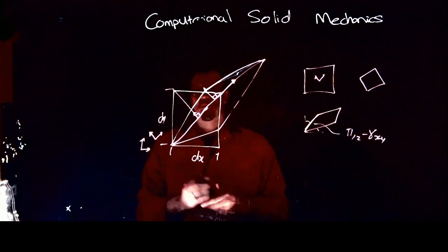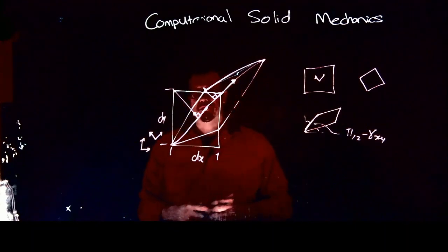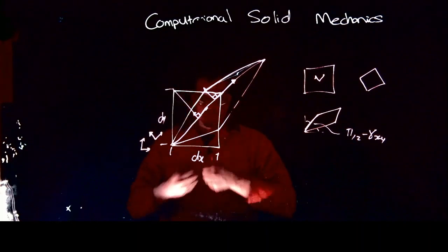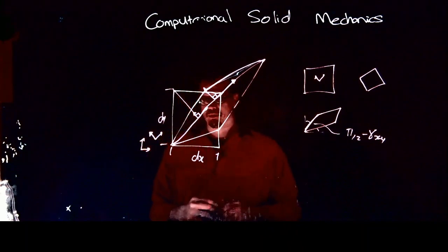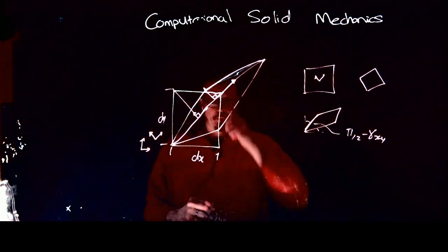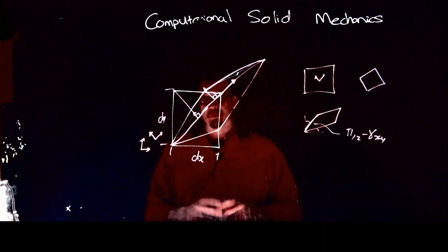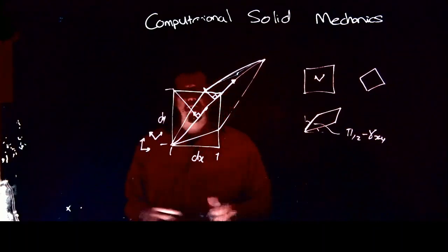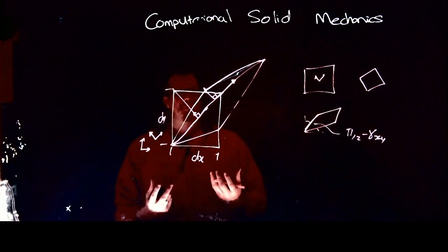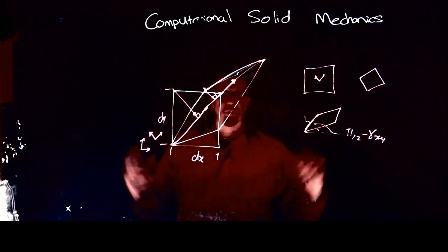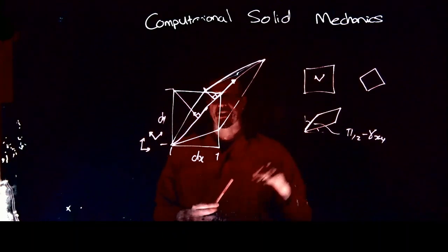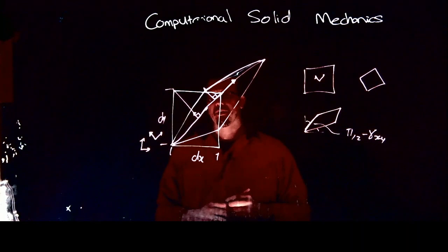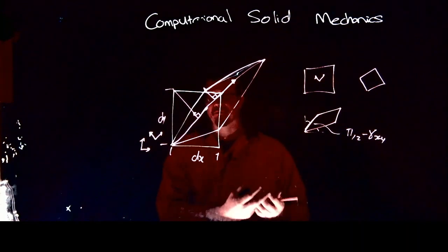The reason why that is important is that materials fail for different reasons. If you have a brittle material, pulling on it, especially tensile loads, is not a good idea. Brittle materials typically fail due to tensile stresses, so tensile strains are a bad idea for brittle materials. But if it comes to a more ductile material that you want to form plastically, then it's really shear that dominates and drives that behavior. So again, you want to see the maximum shear conditions at a point in the material.